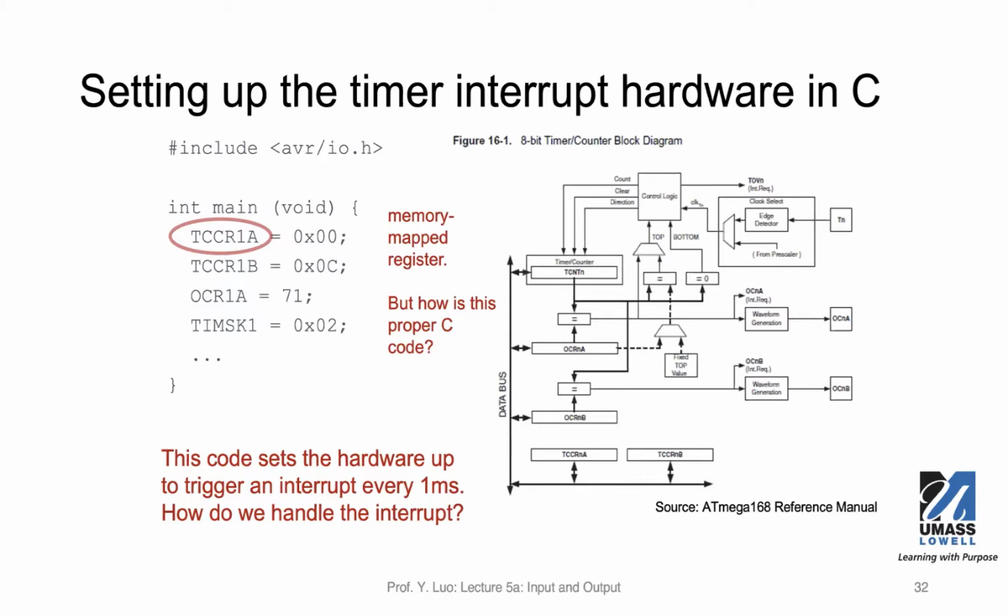You can look up some of the online materials to find out how you set up timer interrupts for Arduino. But as I mentioned, you're not required to use that. It's fine if you use the delay function to count time and counting down. But there are options.